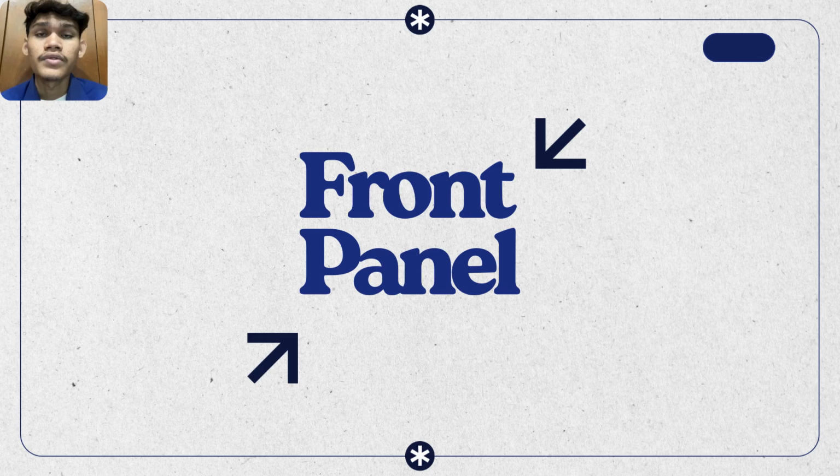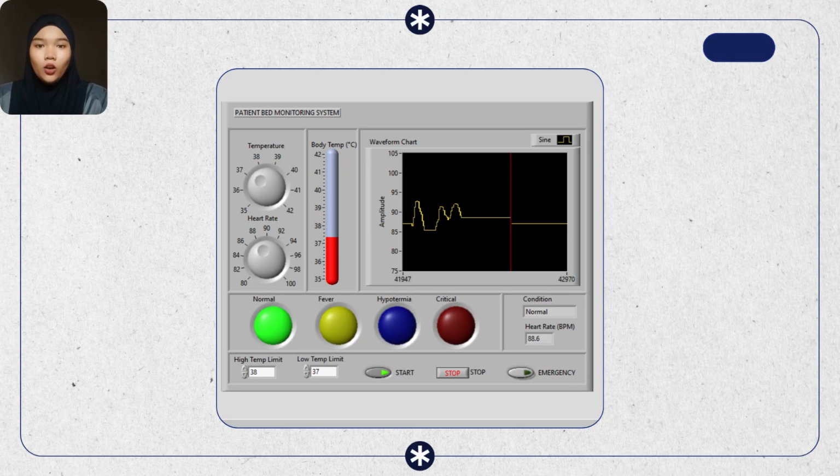This is our front panel for this project. This slide introduces the front panel of our LabVIEW system. On the front panel, we can see the temperature and heart rate controls, numeric indicators, waveform charts, and condition lamps. The colored lamps represent normal, fever, hypothermia, and critical states. The start, stop, and emergency buttons allow the user to control the system easily.